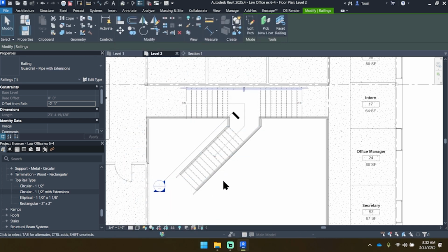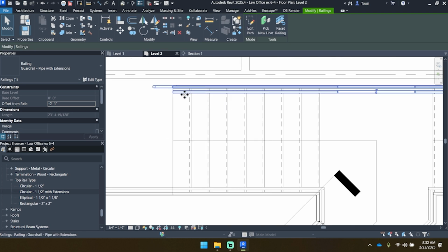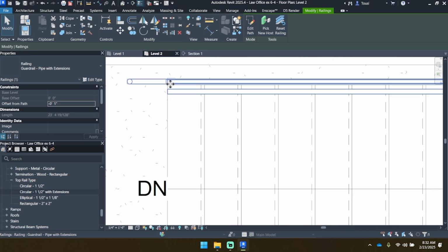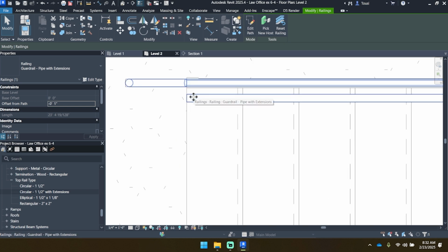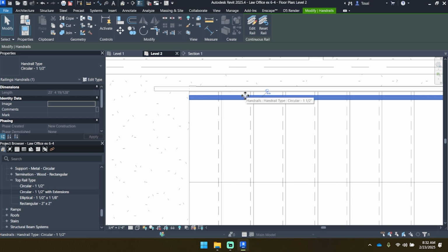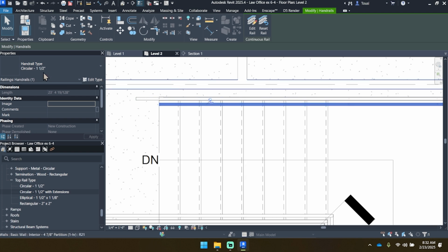The very last detail we're going to add, as you can see on page 8-52 in the bottom right corner under figure 8-3.23, is we want to show that the handrails are going to need to attach to the guardrails and not just be floating and somehow attached. So please get a hold of just the handrail, which is the inner element on that upper piece. Edit its type.